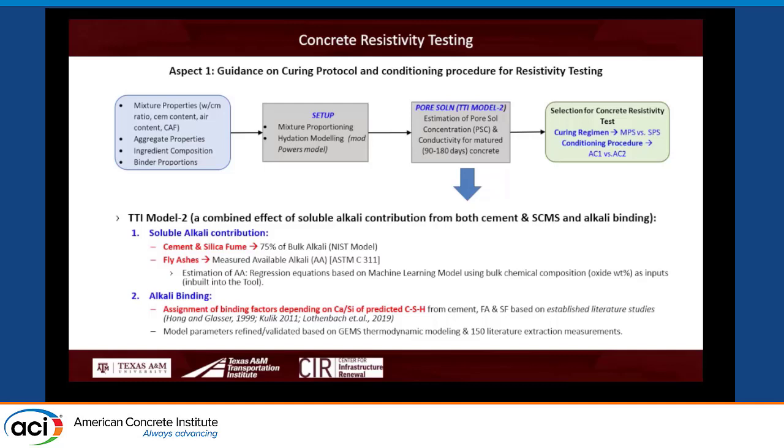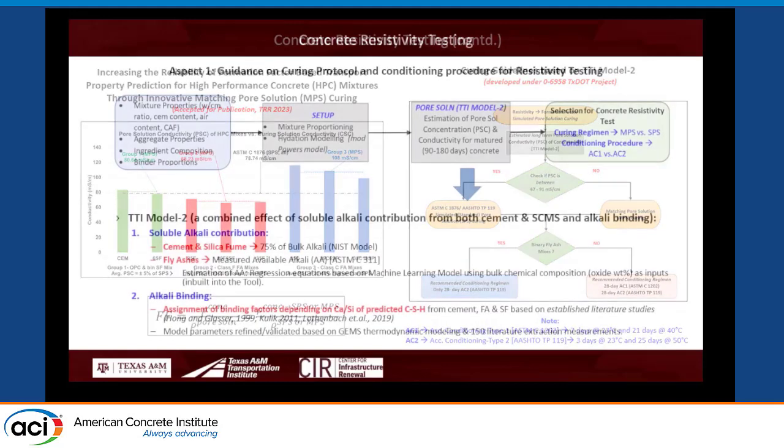It is given by a formula: concrete resistivity divided by the pore solution resistivity. The pore solution resistivity plays a very important role. So we spent a lot of time to improve the formation factor. If you improve the reliability of formation factor, you can use that concrete transport property, and then you can do every performance indicator. So our work is,